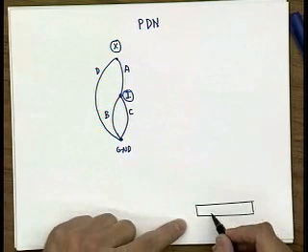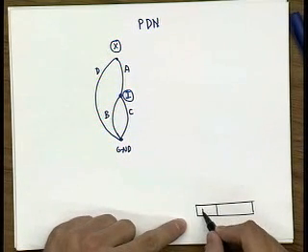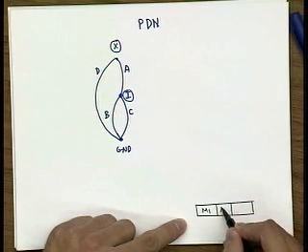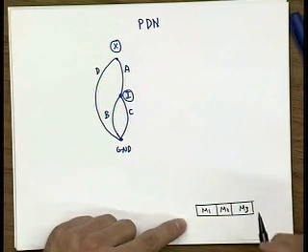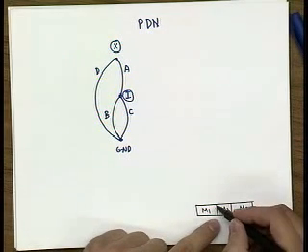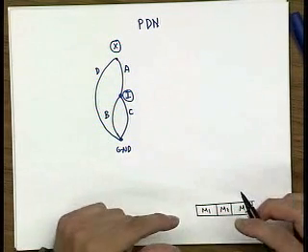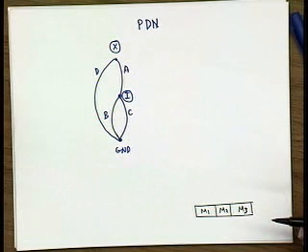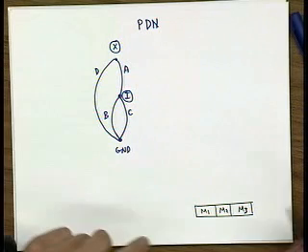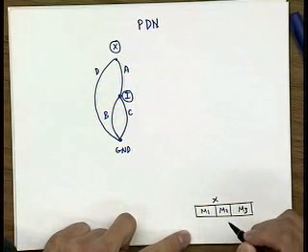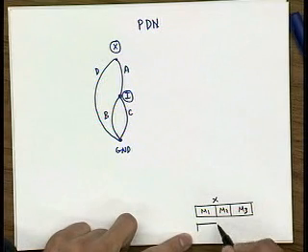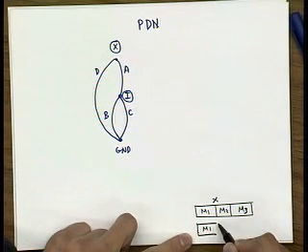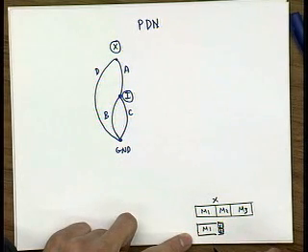This is better than the case where I identify, for example, this transistor M1, this is transistor M2, and this is transistor M3. What happens here is that you not only have uninterrupted diffusion to reduce your area, but in addition you have shared source and drain regions, and you can avoid all these contacts. You have to have some extra space to allow contacts. So let's assume that we can't do this over here. Then you have M1, which has to extend a little bit to form contacts for the source or drain region.